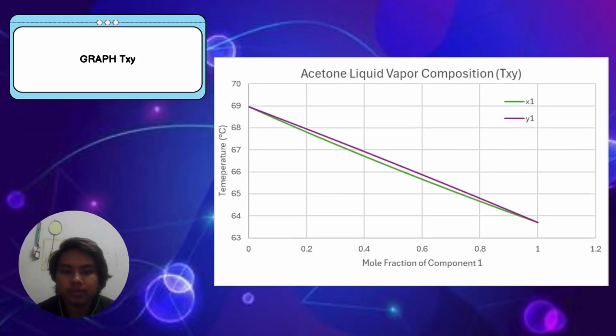This is the TXY graph. The reason we do the TXY graph is so that we can find a few pieces of information from it. One is the phase equilibrium in terms of liquid-vapor equilibrium, dew point and bubble point. We can also find the mixture composition and see the separation process. One application of the TXY graph is that we can use it in distillation and flash columns so that we can design and find the operating conditions.